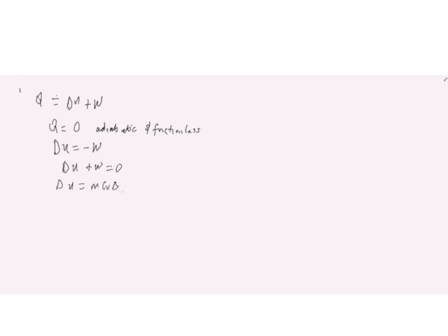We know that dU is equal to m cv delta T, which is the same as m, that is the mass of the gas, times the specific heat at constant volume, into bracket change in temperature T2 minus T1. So we are interested in the new temperature that we have attained after the pin has been removed, and also W. The work is actually done by the gas on the piston.